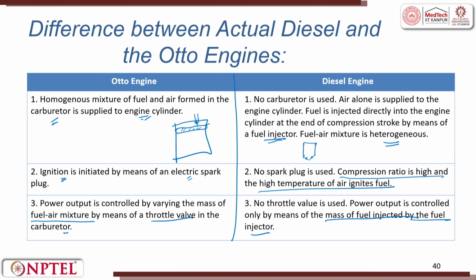If you see diesel, when you fill it up, it is at normal atmospheric pressure. It is a tank filled with diesel. Now, you have an engine on the other end. This engine has to be injected with the fuel, and it is not like a pipe pouring there. So, you have to increase the pressure, not the temperature. So, from the tank we move it towards a pump, and in the pump you try to increase the pressure.